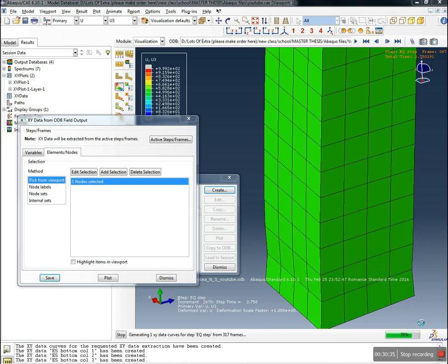I have seen a lot of tall structures in seismic areas that have the first story higher, taller than the other stories. And it's typical for buildings that have shopping centers at the ground floor and just apartment buildings for the rest, or at least this is what I observed, as I said in previous observation just around the city.